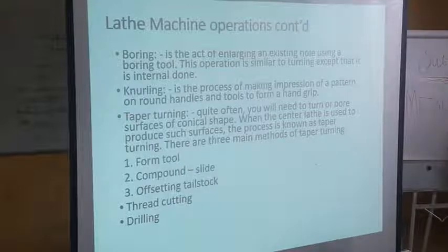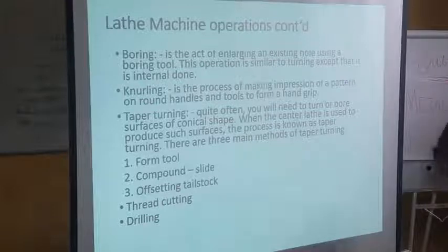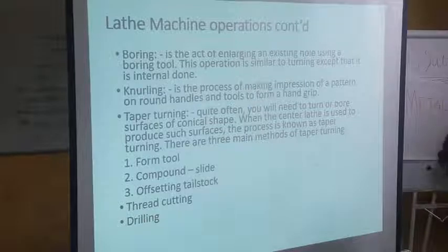But in this context, we assume that the drilling machine has already drilled the hole. Perhaps the diameter you require is bigger than the size of the drilling bits that you want to use. So you take it to the lathe machine and use the boring tool.